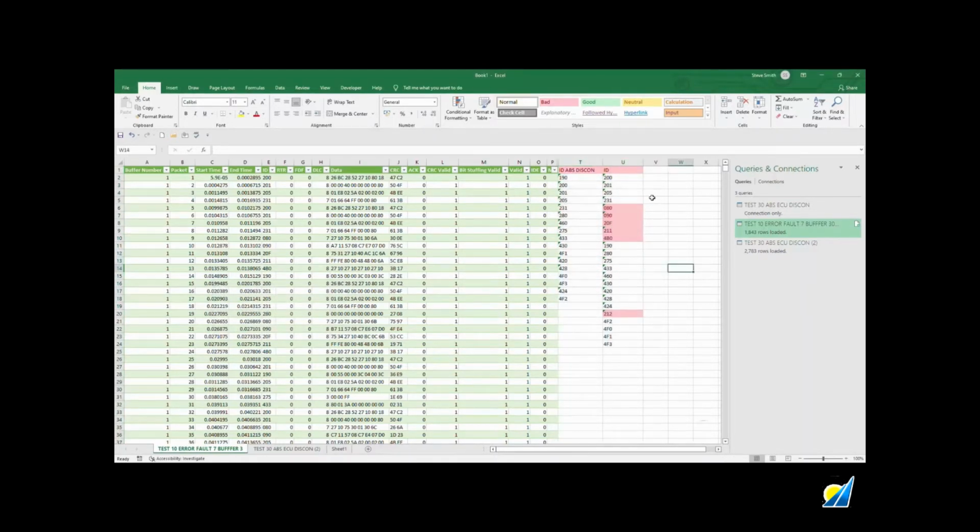So these unique values are 80, 90, 20F, 211, 4B0, and 212. Now, in some ways, they are linked to the ABS ECU. Remember, lowest number, highest priority. Now, 80, we did see being transmitted during the fault condition. So it suggests to me, at this stage, that the ABS ECU was online during the fault condition and was making attempts to transmit. Now 275, yeah, 275 is there. That was trying to transmit, but doesn't appear to be linked to the ABS ECU. 280, yeah, and 200 as well. Okay, so we haven't really identified those, but we know that 80 is most likely linked to the ABS ECU.